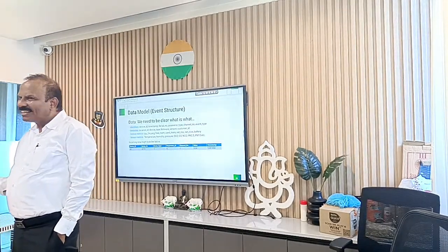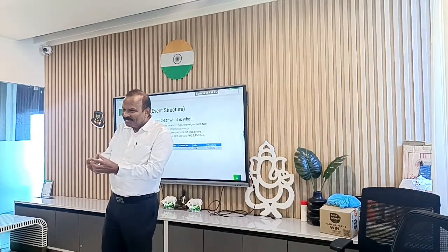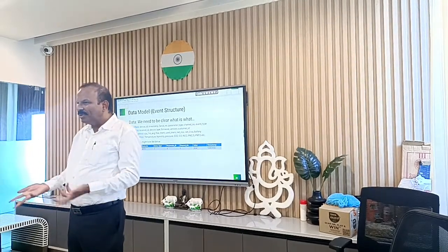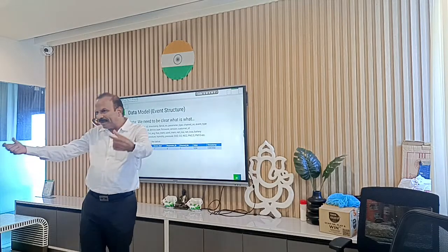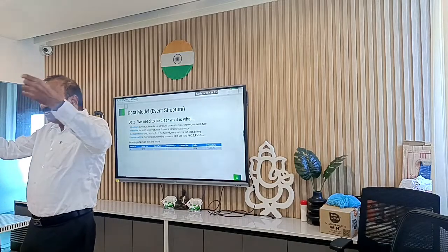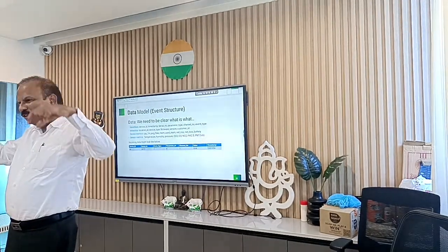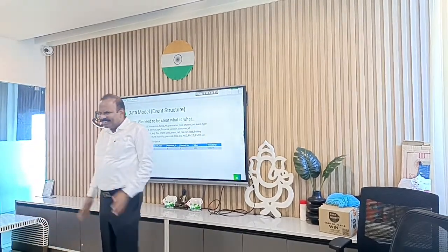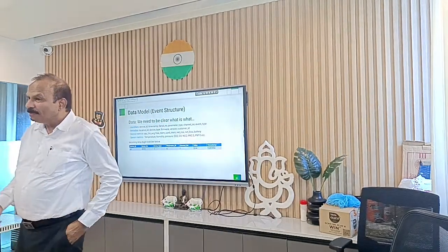In that biggest accident also, there are 3 root causes, not a single root cause. Multiple mistakes, maybe; nobody knows. More than a year back, or 2-3 years back, some of the spare contact wire was shifted for the live wire. Some wire was not working, labeled with some numbers. That was shifted to the spare wire, but the labels were not changed. It looks very silly, but that is the root cause of the accident.